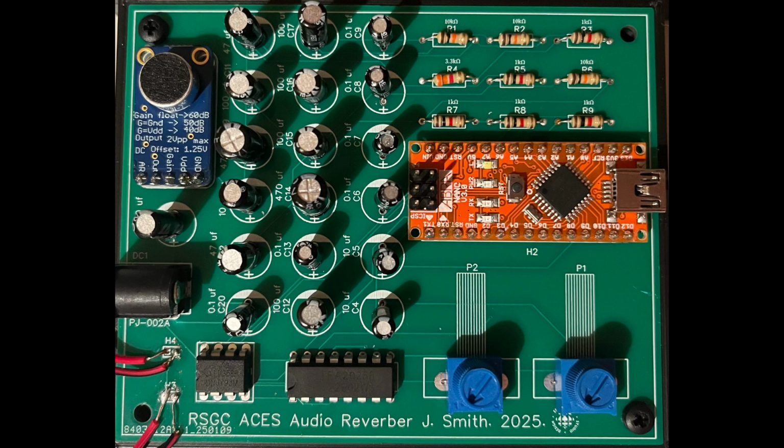Once the PCB is completed, create the case. To keep everything safe and professional looking, design a custom case for the system using Fusion 360 and create the case with the same dimension as the PCB for the length and width. Just add 0.4 millimeters so the PCB fits inside. Then download the case file and 3D print it. After receiving the PCB, solder all of the components on the board, put it into the 3D printed case, and secure the PCB with screws through the screw holes. The final result should look something like this.